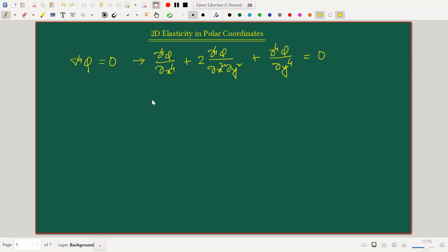First, we could reframe our entire theory starting from the kinematics chapter through the stress chapter, material behavior, as well as all the discussions involved in 2D elasticity, that is to say the plane stress discussions and the plane strain discussions in the r theta coordinate system, and then arrive at the counterpart of this biharmonic equation in the r theta coordinate system. That is the first route.